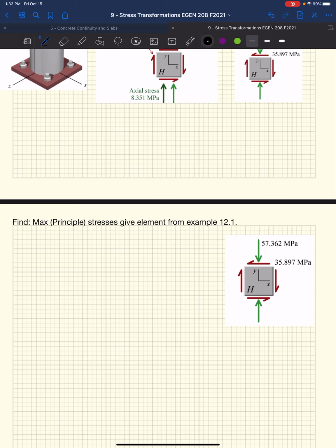So again, we're gonna draw this. That's terrible. I need help. Boom. I know I've got compression, okay? So I drew my Mohr's circle with the y-axis somewhere in the middle, knowing that I'm gonna have a data point on the left-hand side, because normal stress on Mohr's circle on the right-hand side of the y-axis is positive, so we have tension on one side and compression on the other.